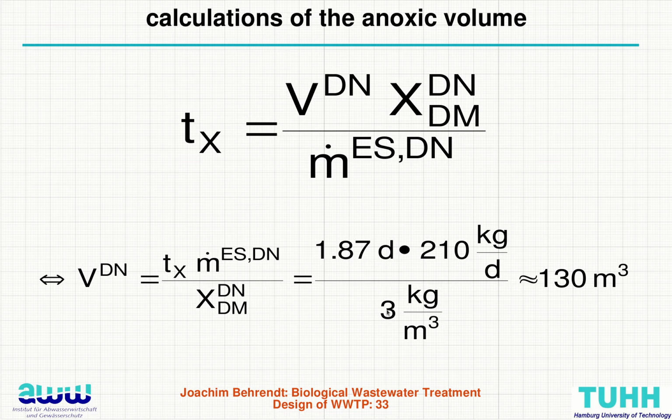If we calculate this, we have a higher growth rate and a smaller sludge retention time, resulting in a little bit less than 2 days. Before it was nearly 6 days, and therefore we have a smaller volume of 130 cubic meters. We had estimated 200 for denitrification beforehand.